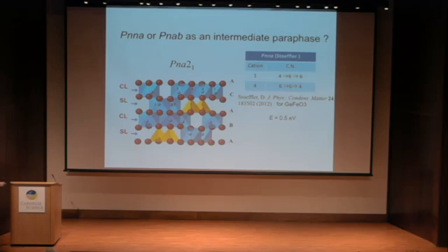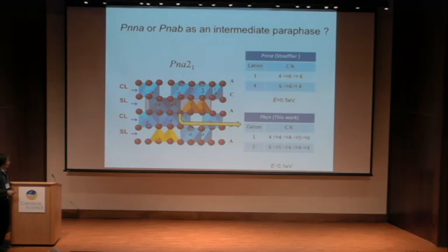And in this case, the polarization switching occurs in the tetrahedra and octahedra, both in the spinel layer and the corundum layer. And in this case, the activation energy is calculated at around 0.5 electron volt. But in our model, we use PBCN, and in this case, the activation energy is decreased down to 0.1 electron volt.